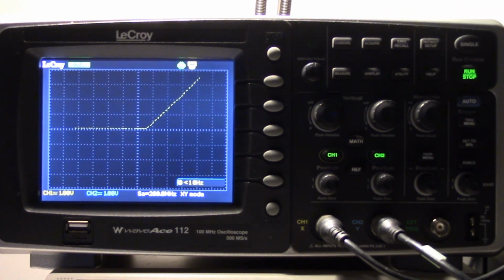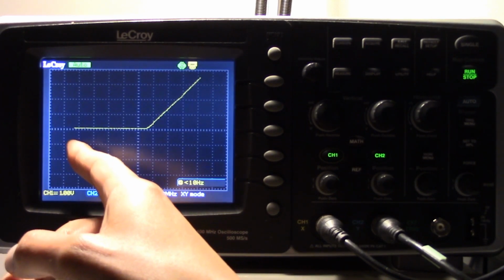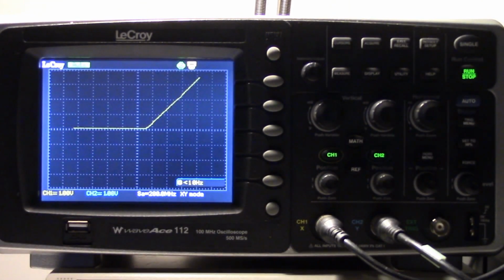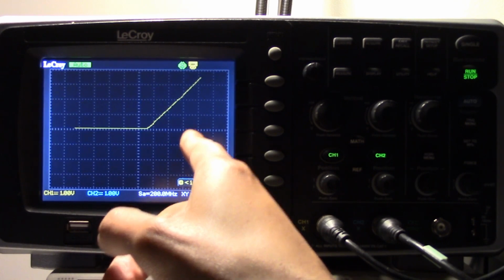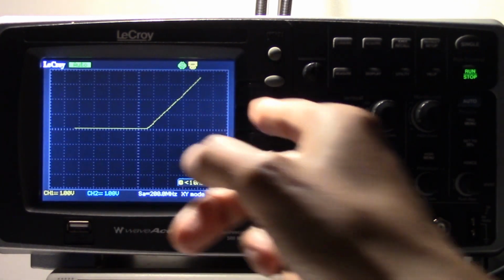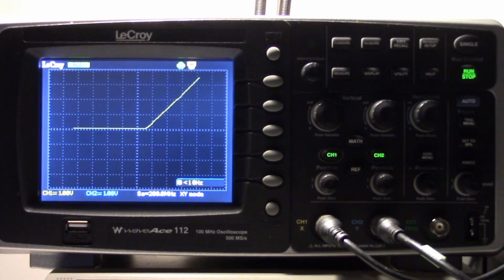According to this, we're going a little bit below -4 volts. That's probably why I had to have the trigger set to like -5. That's still okay, as long as we cover the range. I wanted to make sure I covered the range. And over here, at 1 volt per division, I'm a little bit more than a positive 4 volts, but that's okay. At least I'm covering the entire range.